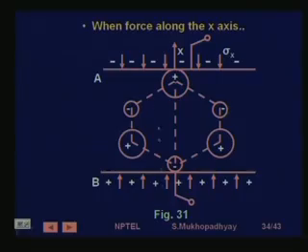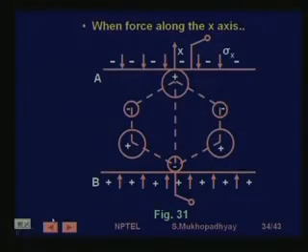When it becomes deformed, it generates an electric field inside, and that leads to accumulation of charge on the two sides, and obviously that will give you some voltage difference, because the electric potentials become different at the two ends. So it is this voltage difference that is to be sensed, or the charge which is to be sensed, right.